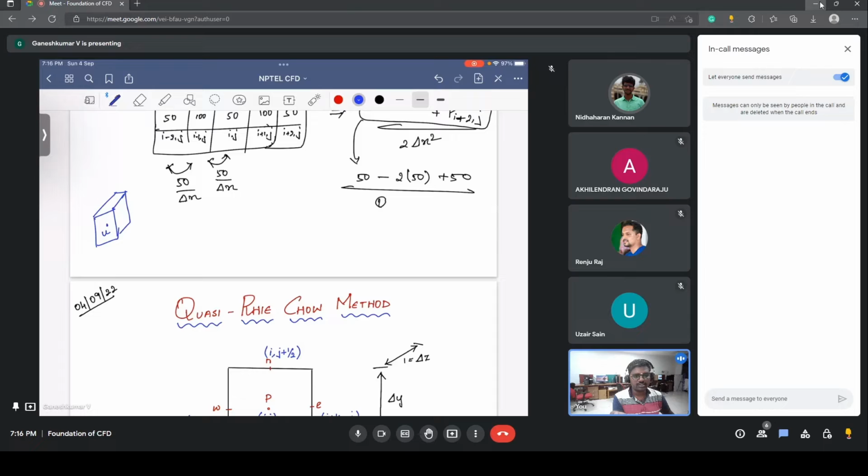Let's say there is an energy equation; let's write it as an enthalpy equation. Similarly, there will be a convection term for enthalpy, and there will be the del square T term, plus some more terms, some q addition. There is no link between these two sets of equations: continuity and momentum on one side, and the energy equation, where temperature comes in, on the other. So you need not find temperature to find any of the other quantities.